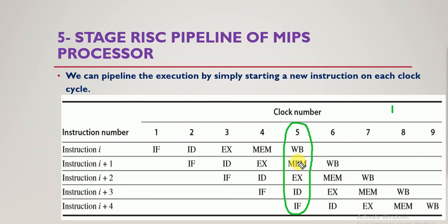So what was our initial imagination? One instruction takes 5 clock cycles. That is our initial assumption normally. But when we implement pipelining, from the 5th cycle onwards, we can see that all the operations required for a particular instruction are executed, each within a single clock cycle.